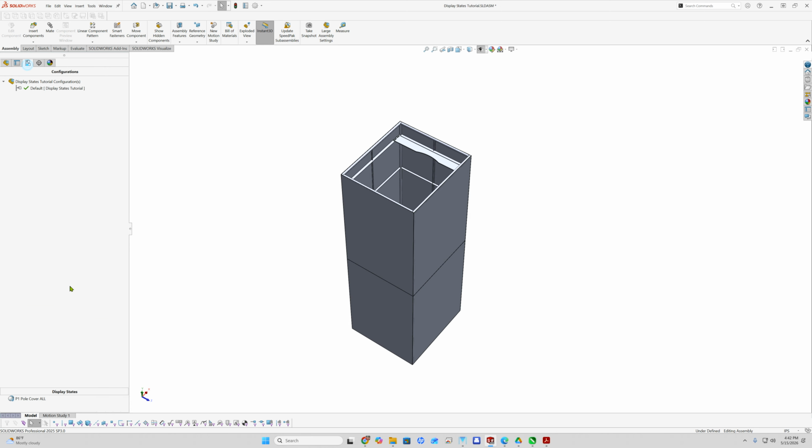Back to the display state, when you right click, you can drag that up and it helps put these up there where you can see them. Right click the existing display state and add a display state. Now you notice it activated the new one and it grayed out the old one. When a display state is grayed out, that's the only time you can rename it.